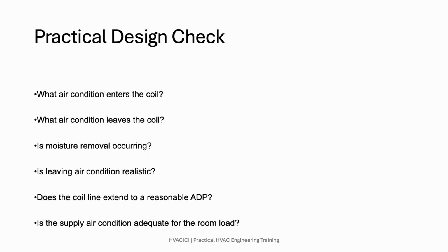In a real design review, check the entering coil condition, leaving coil condition, and whether moisture removal is occurring. Then verify whether the leaving air point is realistic and whether the coil process line extends to a reasonable ADP.